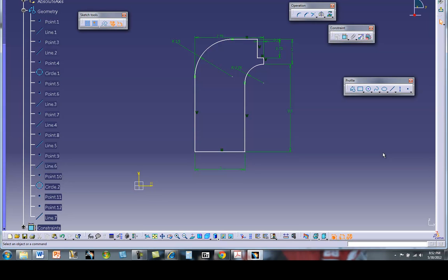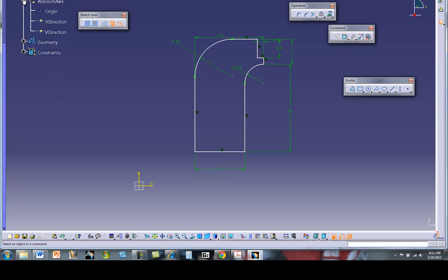Now let's lock down this location. So again, I'm going to pull this up, open this out, and say, okay, I want to basically go from this point right here to the origin. Again, I'll make this a horizontal measure, and then from that point, let's go in again, geometry.